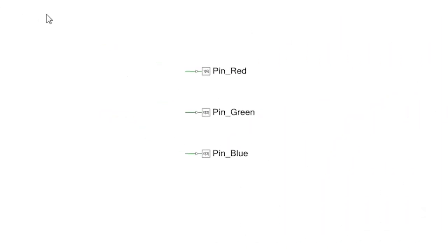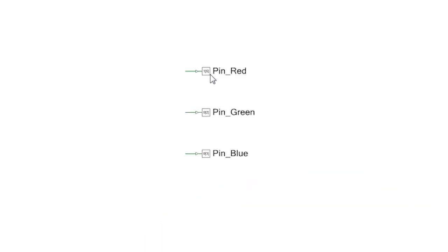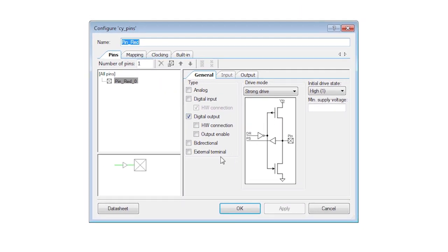Before I talk about the input pins, I have to change something from the first lesson that has been giving me the heebie-jeebies, which is definitely not a good thing. If you look at the schematic, you will see the pins, but there's no indication of what they do. If you showed this to a colleague, they'd think you were crazy, and they would have to rely only on your pin naming to understand the intended functionality. Let's fix that by documenting the LED circuit by using the library off-chip components that we provide.